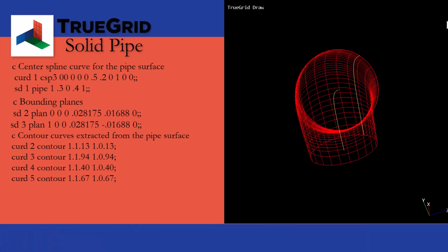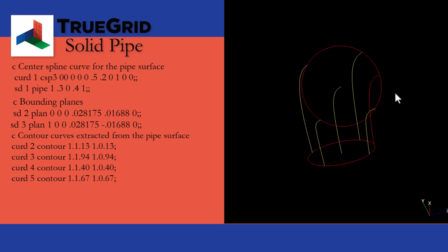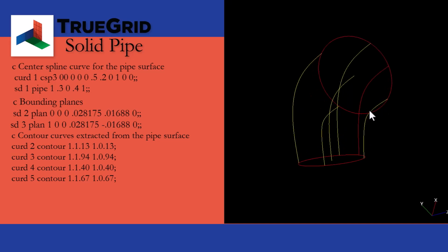If more than one surface is needed to form the outer surfaces, this method of extracting 4 contour curves may not work, since a simple contour like these can only be extracted from one surface. Spline curves can be used, but they may only have the control points in common with the surfaces. This is acceptable since it is not essential that all 4 curves be precisely on the outer surfaces. The projection will pull any stray edge nodes which were initialized to a curve onto the surface of projection.